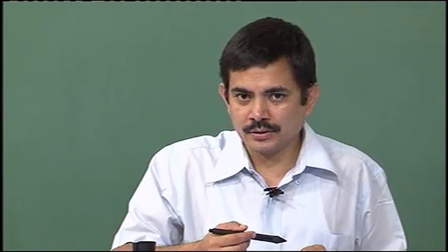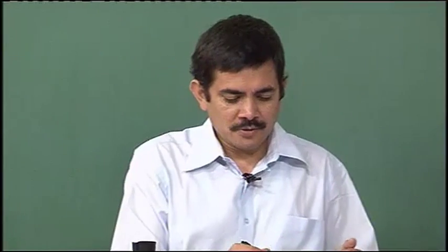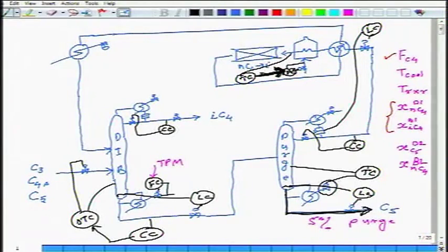That's how it turns out for this example, and that actually makes sense. By allowing more or less to leak out, this stream is small, it won't really make a big difference. Having back off here, what will it do? It will essentially limit your ability to, if the amount of NC4 that was recirculating around was, you could have put it down to 1%, now you are putting it down to 1.5%. So the economic penalty for back off from boil ups is not that much. Economic penalty for back off from furnace duty is quite severe. Therefore, we did what we did.